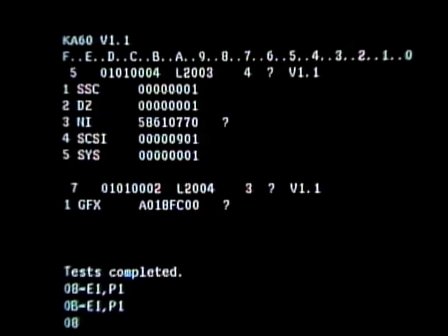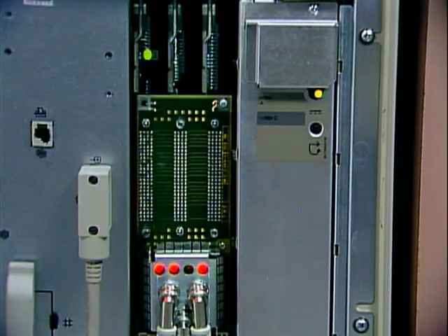The Power-Up Self-Test console printout lists only one entry for the entire graphics subsystem when it encounters an error. There are two ways to interpret a graphics subsystem error down to the failing FRU. You can use the VAXstation 3520-3540 maintenance guide to decode the error code listed on the console, or you can determine the failing module by interpreting the LED codes on the base module and the graphics front plane.